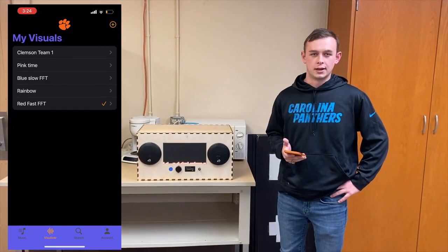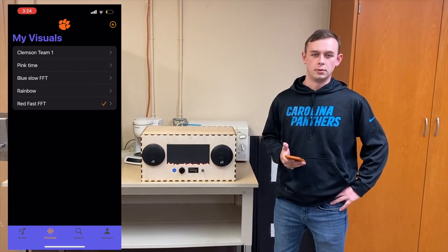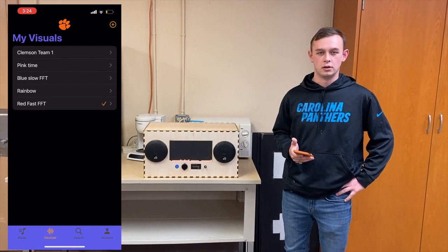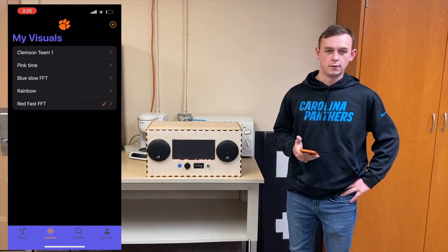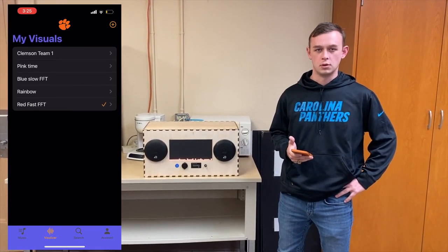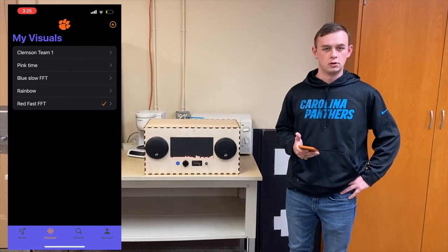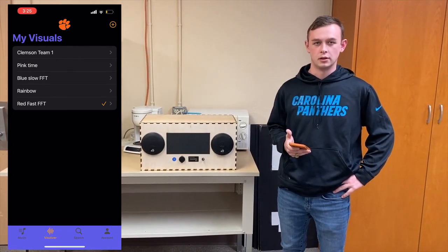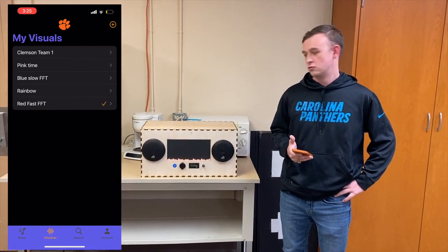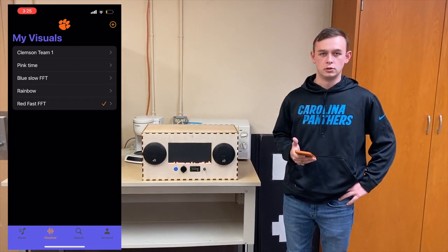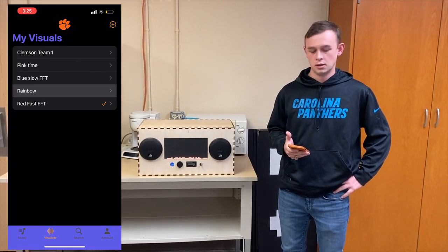The Bluetooth LE connection, we actually did have to develop a little bit further. We made this a UART connection, so there's a UART bus that the Pi and the phone or connected device can communicate on. And this we are using just to update. We pass a live string, which conforms to our protocol. And our Pi knows how to interact and interpret this data.